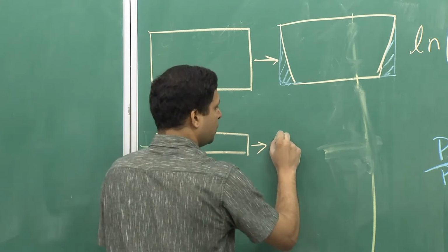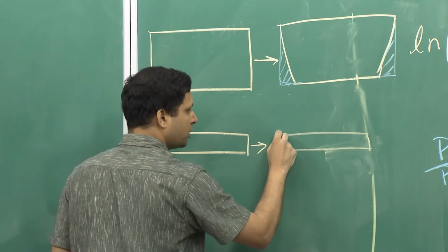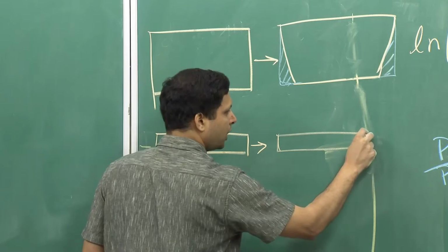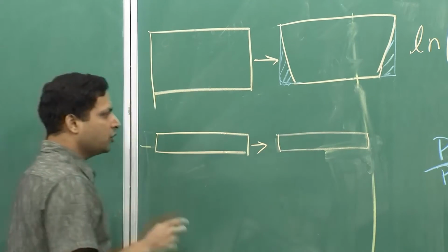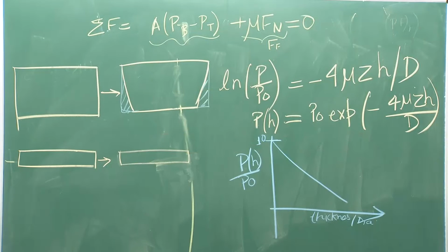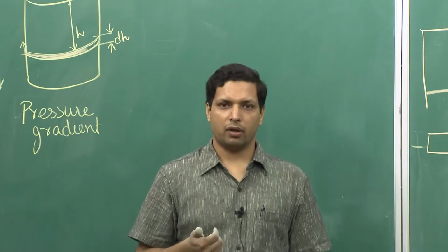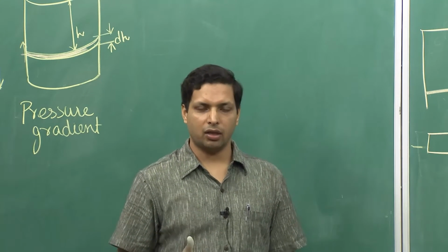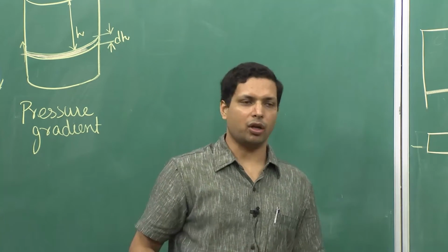So, if you were to make this, the shrinkage would be so small that it may be within the tolerable limit, and that is one reason you see that most of the time in powder processing we use only 2.5 dimensions. That is, in the third dimension you do not have a much larger length or height of the component, because you want to keep it smaller.